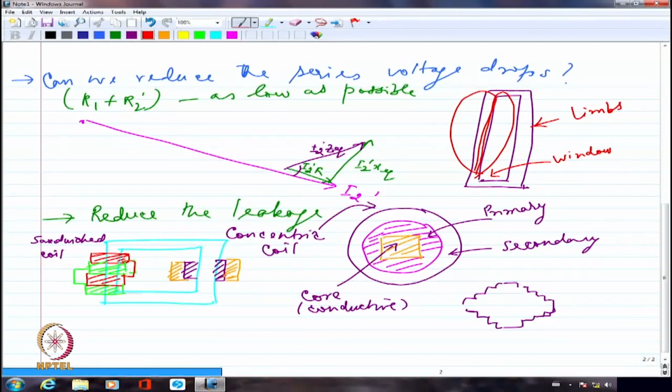If the reluctance increases, the number of lines escaping into the air gap will decrease. If the number of lines escaping into the air gap decreases, the leakage decreases. The total number of lines confined to the core will be increased correspondingly. So, three ways of reducing the leakages.